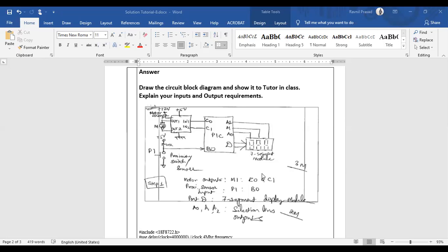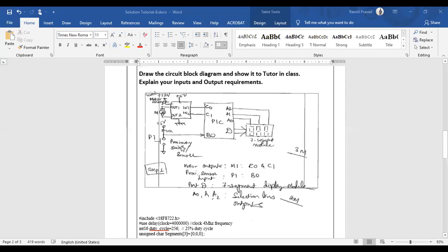Also, when we are using a proximity sensor, we can count it as a switch, right? As the item passes by, it will give a high or low logic. So that high and low logic is basically associated with a switch as well. We can model that in this particular case as a switch, so we'll model the proximity sensor as a switch.